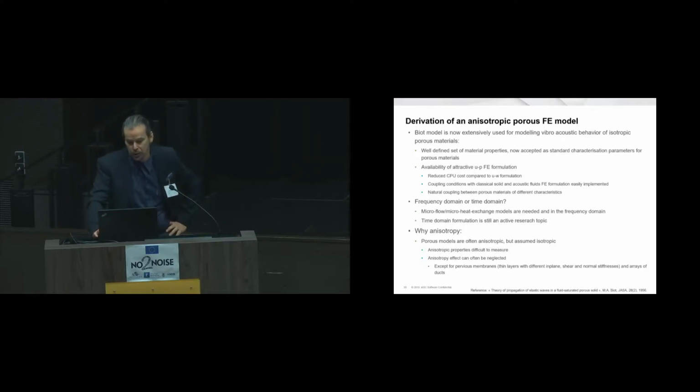They are much more efficient in terms of degrees of freedom than the other formulation based on fluid displacement, because they go from 6 to 4 degrees of freedom per node. And the natural boundary conditions are also useful in the sense that they naturally express total stress and allow us to easily impose impervious membranes on the surface of pores. That's why they couple easily with solids, and that's why they are useful in themselves also as natural boundary conditions.